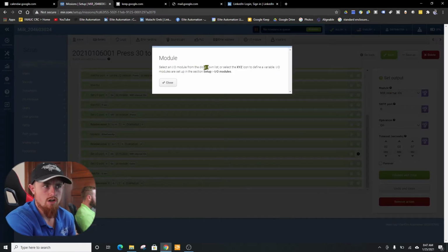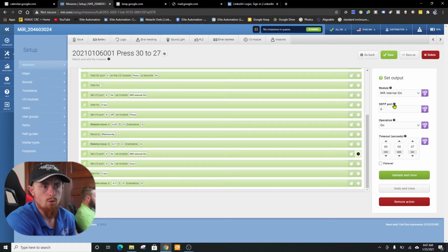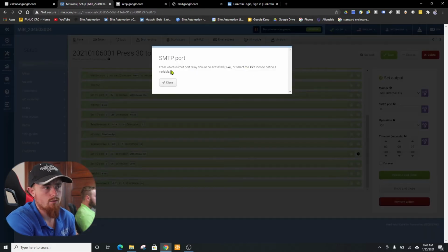But then you can do stuff like put a PLC on it and do a lot of processing on an onboard PLC if you need extra IO points. And you can even get creative with it and add a wireless hub onto it and even do remote IO, like point IO with Allen Bradley, and use a Wi-Fi router if you can get away with it, if your customer's okay with it, and have a ton of capabilities at that point.